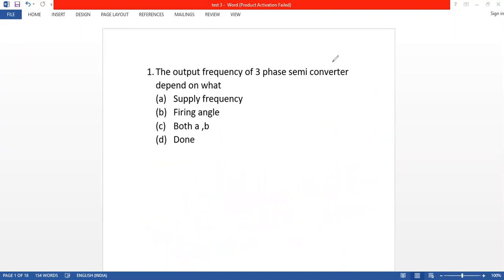Okay. Now tell me, does a transformer operate with DC? With DC? The answer is yes. You don't say that a transformer doesn't operate, but the condition is that you should not allow the transformer to saturate. I will discuss this in a separate topic. Right now I am giving it as homework.